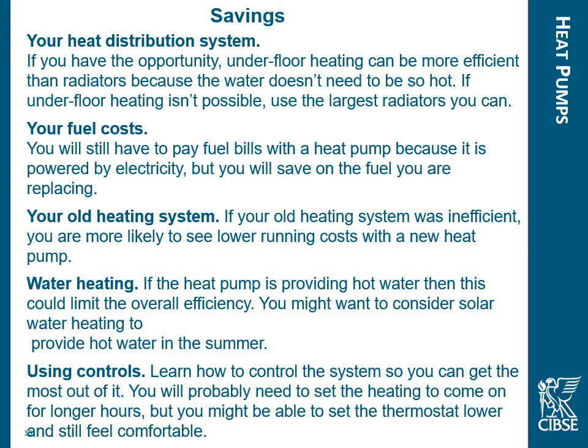So if you have the opportunity for underfloor heating, it'd be more efficient than radiators because the water doesn't need to be so hot. You'll still have fuel costs, but they'll be electricity only. You won't have a gas bill, it'll just be electricity. If your old heating system was inefficient, you're likely to see lower running costs, but you've got to take into consideration that electric is expensive as opposed to gas. So electric at the moment is about 4 times more expensive than gas. What we need to do is think of better places to get the electricity from, which we'll look at later on in the course.